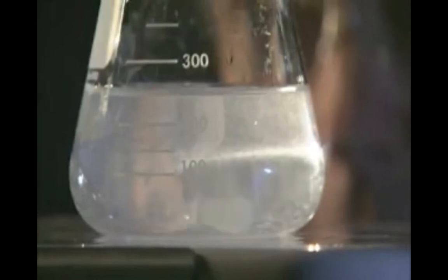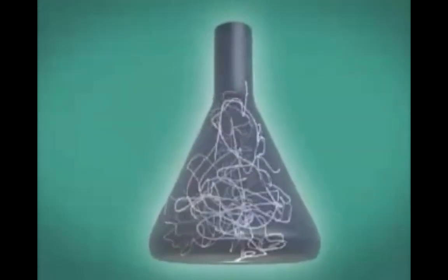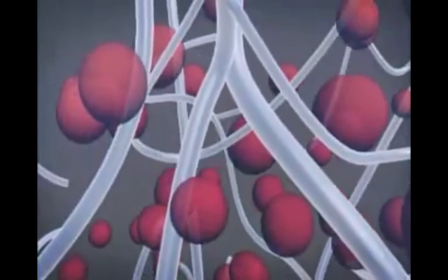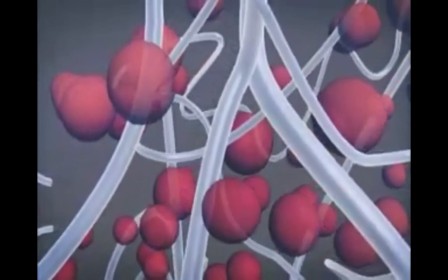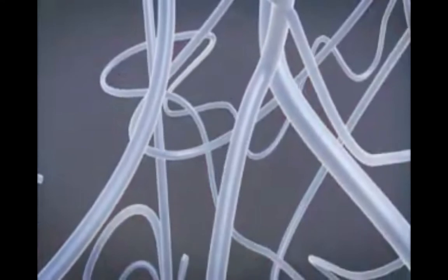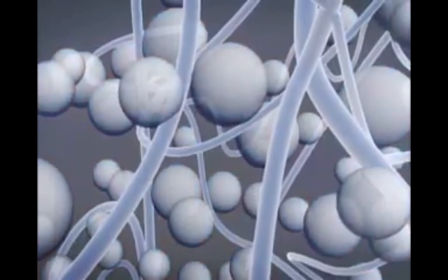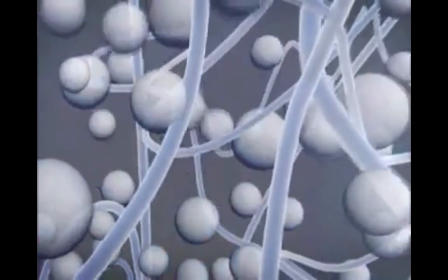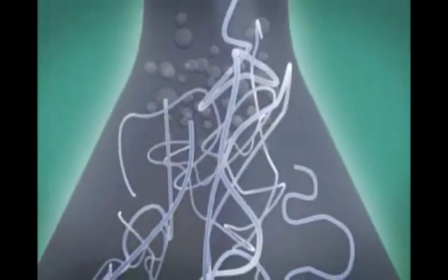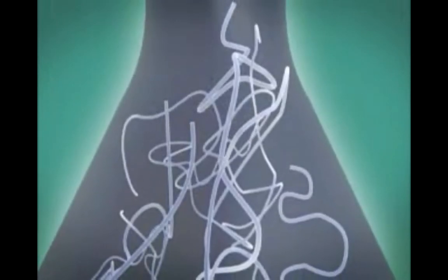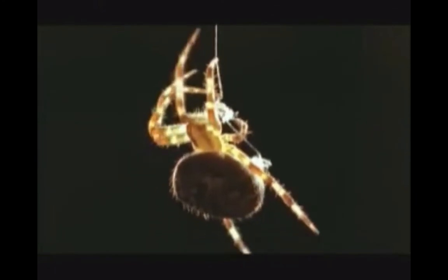Aerogel is made from a jelly-like substance, part liquid, part solid. The solids are fine chains of silica, surrounded by alcohol. To dry the gel, the alcohol is replaced with liquid CO2 under high pressure. As the pressure drops, the liquid CO2 becomes a gas. It bubbles away and leaves behind tiny air-filled pockets that are 1,000 times thinner than a spider's web. This elaborate honeycomb of air blocks heat instantly.